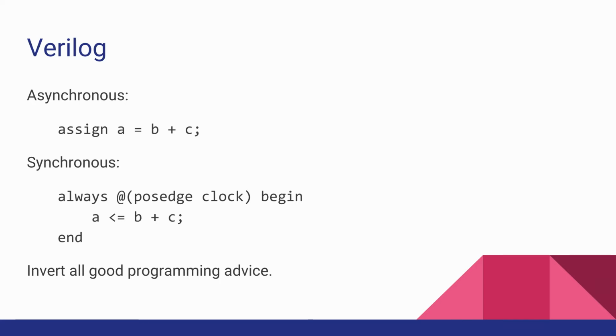When I started FPGA programming, or before that, I kept asking people who knew better, so what clock rate do you run FPGAs at? And they looked at me like, if you're asking that question, then you don't understand what an FPGA is. And now I understand what they meant, which is: how fast is this? Well, how fast is B plus C? It's really fast. You could probably run this at many hundreds of megahertz. Not like the 3 gigahertz of an Intel, because that's specifically made for that, whereas in here you've got this very generic fabric. But you can run this at hundreds of megahertz, no problem.